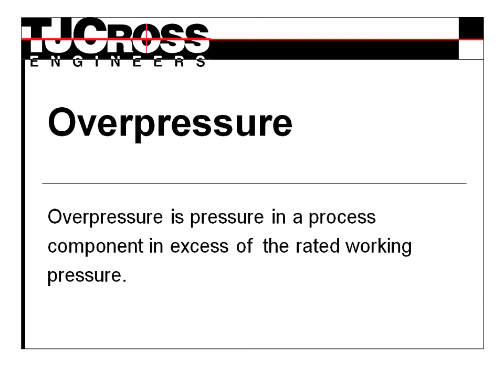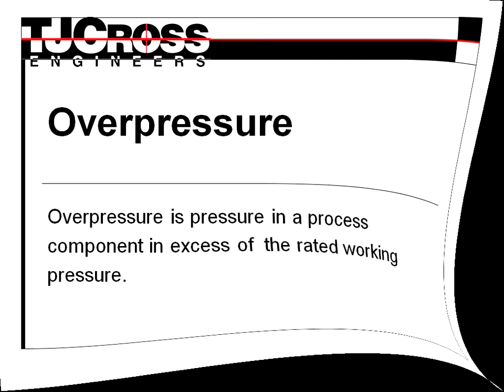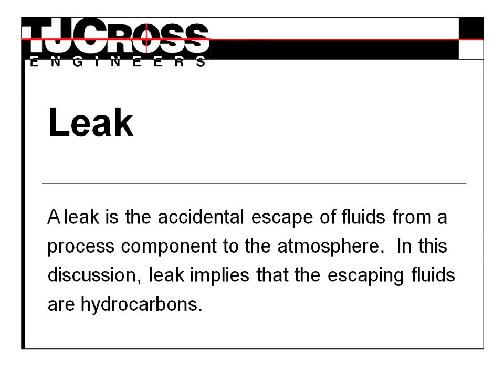Overpressure. Overpressure is pressure in a process component in excess of the rated working pressure. Leak. A leak is the accidental escape of fluids from a process component to the atmosphere. In this discussion, leak implies that the escaping fluids are hydrocarbons.